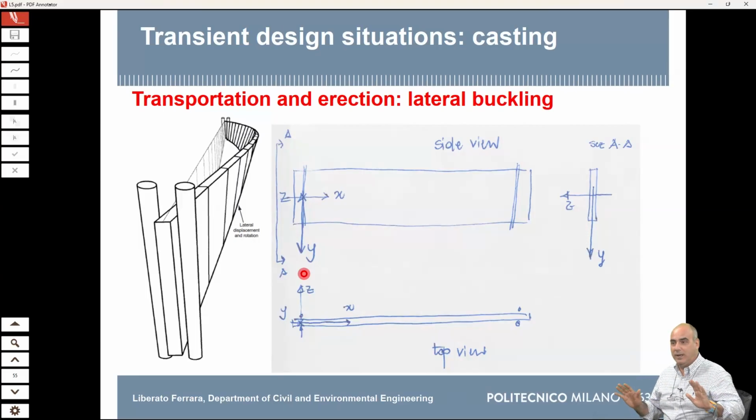Whenever you have to deal with a structural mechanics problem, the first thing is to set a reference system, because from that onward, everything will depend. This is what I always tell my students when I ask a question at the exam and they immediately write the equation. And I say, okay, that equation as it's written, in which reference system is it valid? Because if you change the reference system, it's not that the equation changes, but the signs may change.